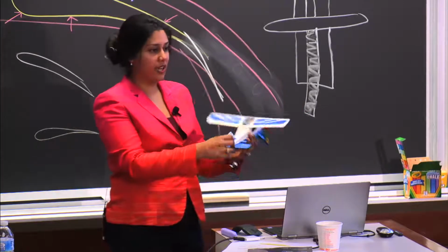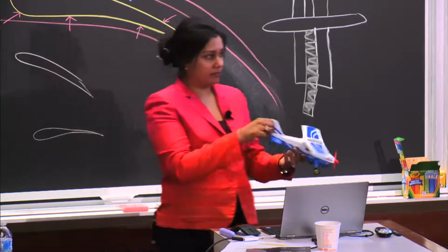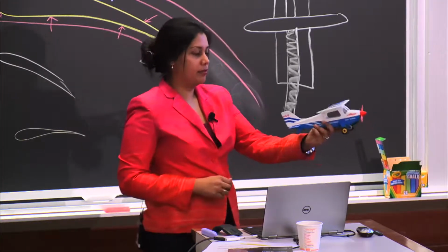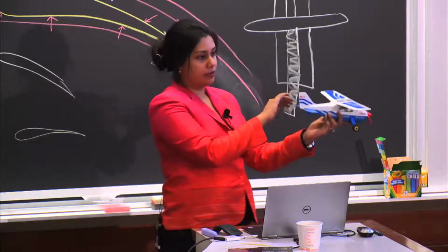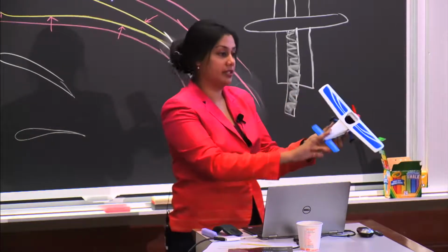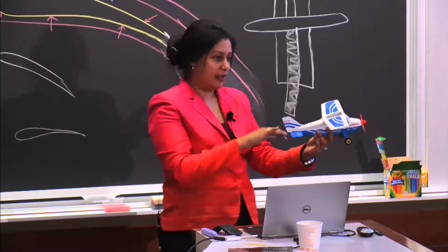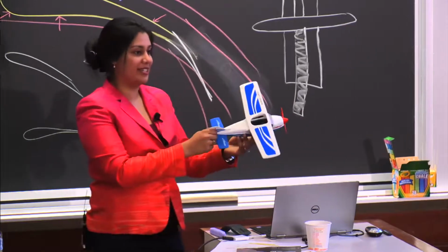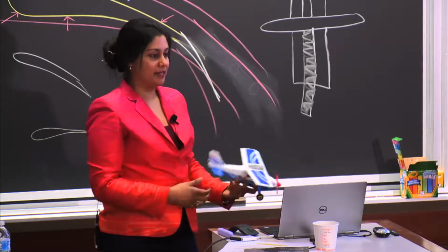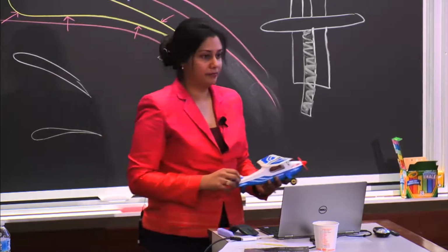These are connected angles, but what we've observed is primarily that the air, when it hits the vertical stabilizer, is the biggest surface that's pushing it, and the angle that it's at. So if you sum it all together, yes, I'm quite confident you'll get some roll, but the biggest thing that you notice is the yaw.